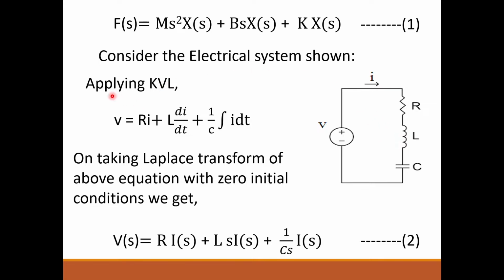Now applying KVL, you can write down the differential equation. V is equal to R into i plus L into di by dt plus 1 by C integral of i dt. So this is our differential equation, applying KVL for this circuit.